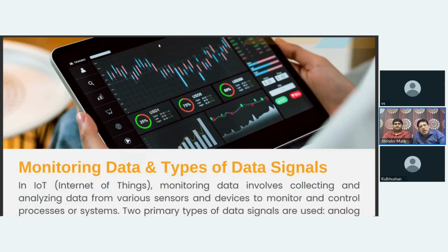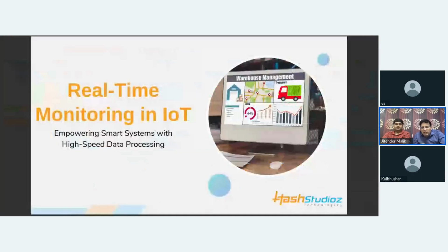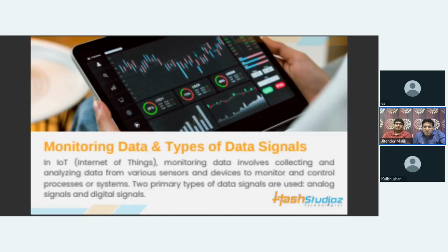In that seminar, we presented three types of IoT gateways, and then we showed a live demo where we captured the data from energy meters in multi-slave mode. One gateway was able to capture data from four energy meters, and then we showed the data on the dashboard, and we displayed the data over MQTT in JSON format.